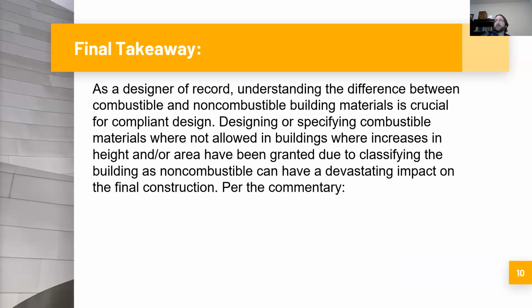So let's see here, the final takeaway: as a designer of record, understanding the differences between combustible and non-combustible building materials is crucial for compliant design. Designing or specifying combustible materials where not allowed in buildings where increases in height or area have been granted due to classifying the building as non-combustible can have a devastating impact on the final construction.